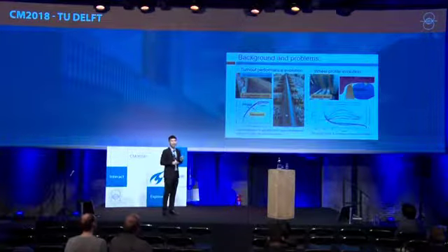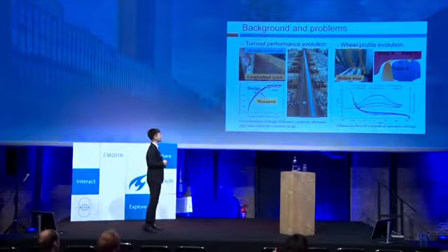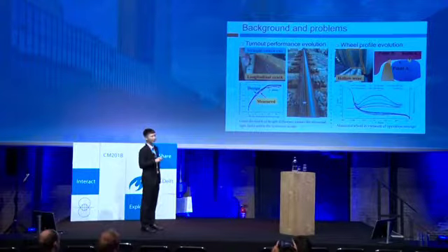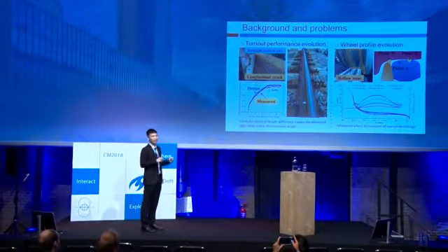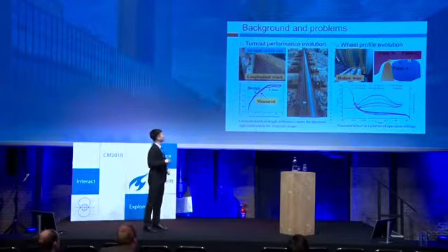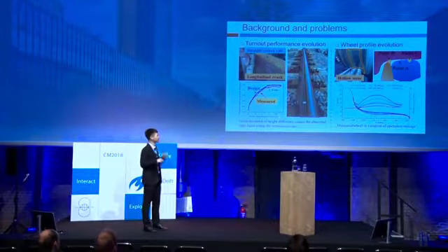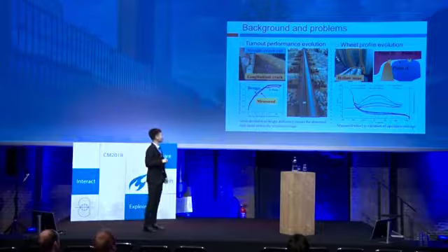As we know, the wheel-rail relationship in a turnout is more complicated than that in the interval line. The figures on the left side show the typical damage types in the Chinese high-speed railway turnout. The figure in the upper left shows the longitudinal crack on the straight switch rail side, and it is caused by the incorrect grinding method. The figure in the lower left shows that the great deviation of the height frequencies between the stock rail and the switch rail causes the abnormal light band within the transition scope in the turnout.